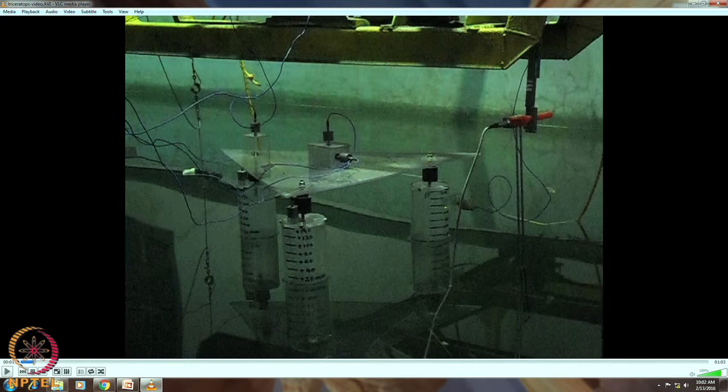Friends, let us also look into a small video which tells you how the isolation between the deck and the BLS happens because of the ball joint. Please pay attention to the screen now. This is a triangular deck plate which is connected to the buoyant leg structures. You can see the draft design for the buoyant leg structures which are calibrated here. You can also see the instrumentation being used for measuring various degrees of freedom in response. These are the ball joints, and we are also measuring the acceleration and inclinations in the ball joint as well.